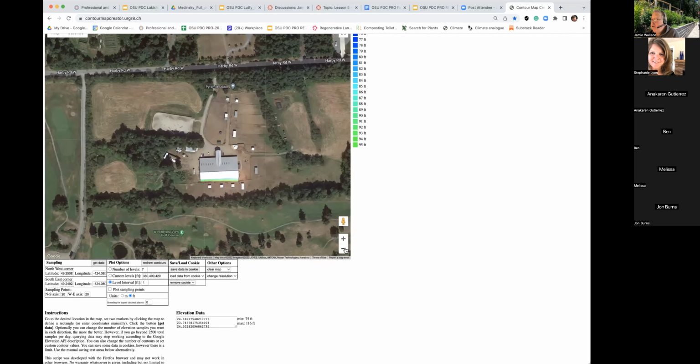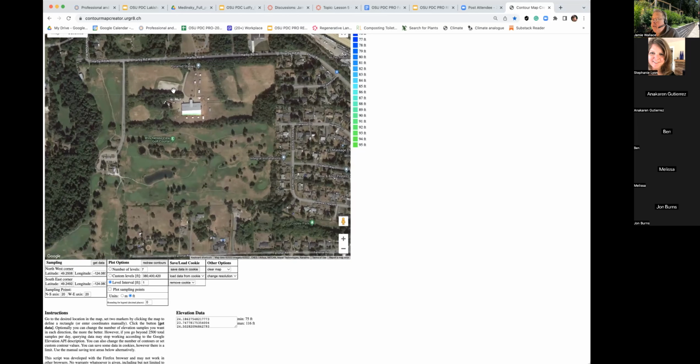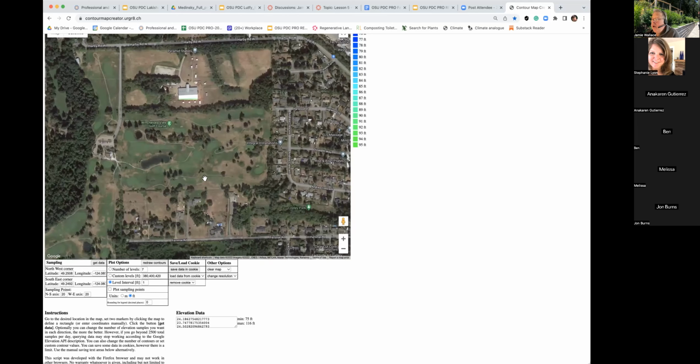Like this property here, I know it's about 25 acres. That's going to be quite different. You have a roadway here definitely to factor in, and one here. But I know with this property, the slope's going up, so in all likelihood the micro watershed's actually going to come all the way up to this road here. So this would be quite large. And I do know this property gets a lot of water flowing through it. So when you're on acreage, look a bit beyond, but do factor in the roads. That is a big part of the micro watershed calculation, being a constraint there.